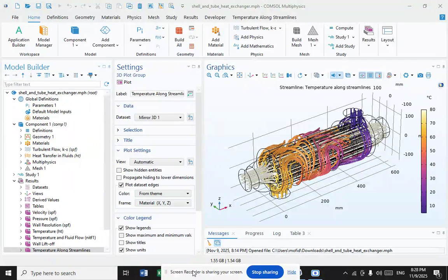Surface condenser is the most common type of condenser, where it includes a water supply device. And this simulation displays a two-pass surface condenser. The pressure of steam at the turbine outlet is low, where the steam density is very low, where the flow rate is very high. To prevent a decrease in pressure in the movement of steam from the turbine to condenser, the condenser unit is placed underneath and connected to turbine.